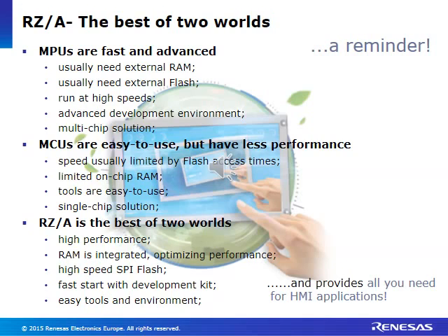As far as microprocessors are concerned, performance is usually more important than cost. This means there is a big focus on high-performance cores with high operating frequencies, high DMIPS per megahertz, and multi-core superscalar hardware architectures. The operating system is also very high on the list. Flash and SRAM are usually external with microprocessors, as these have to be scaled heavily in high-performance applications.